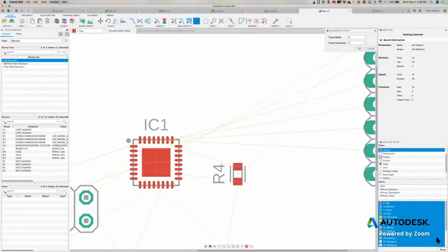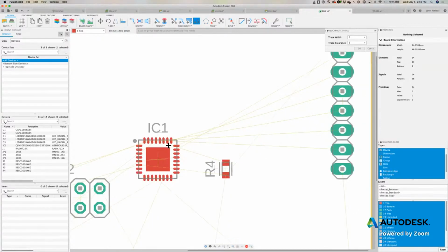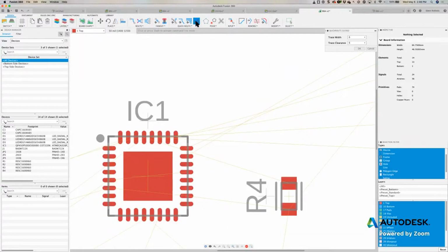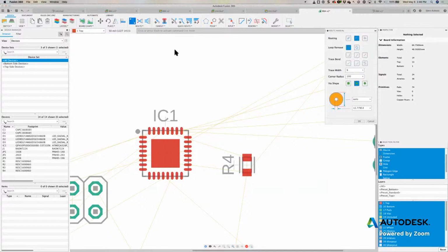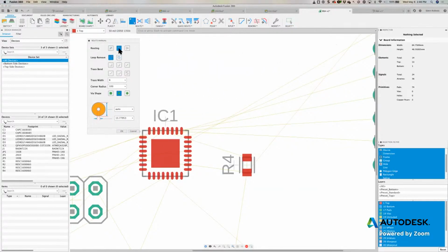Oh, as I said earlier, if you hear donks, it's just you need your selection filter. You got to reset the selection filter. So let's go here and I'll just use sketch routing that we have here available. Okay, so when you click on the manual route option, you get by default the walkaround obstacle avoidance automatically enabled. So in other words, if I start routing this line, it's going to automatically route on that layer. This is my active layer, okay?